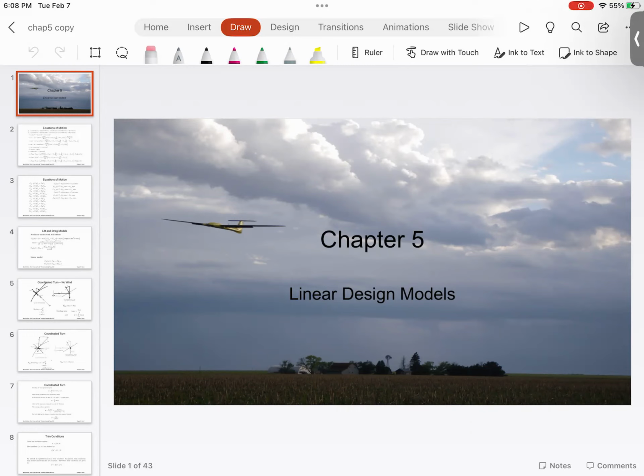So when you start working on a tilt rotor, which takes off as a helicopter and then flips into airplane mode, these 2 flight modes need to be incorporated in the mathematical model of the aircraft. And what you do is you change the forces and the moments by the control surfaces.